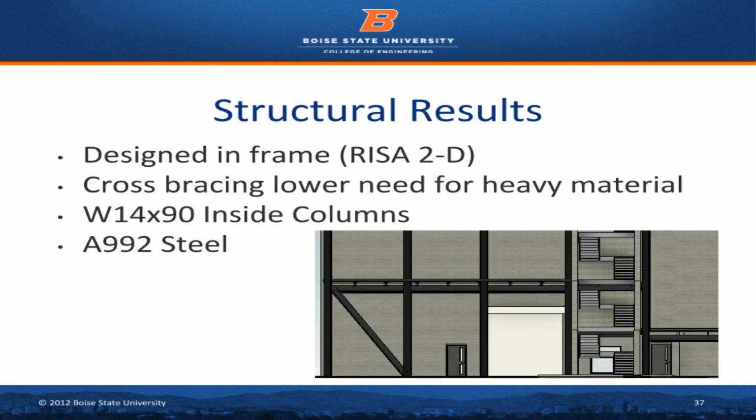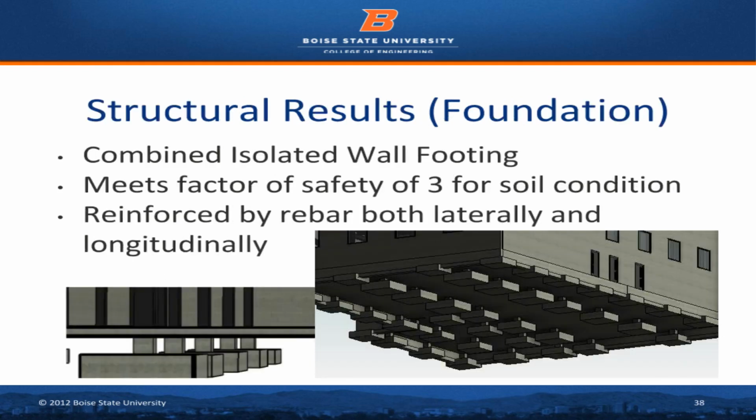As for the columns, we decided that a brace system would be the best way to design for both notional and earthquake loadings. This was all done in Revit 2D. Given that the connections were not to be designed, a moment-resistant connection setup would be the best for this application. We also decided that cross bracing would be necessary to reduce deflection and ultimately reduce the size of the material needed. Next, we decided an isolated footing would be the easiest and most affordable solution for a foundation design.